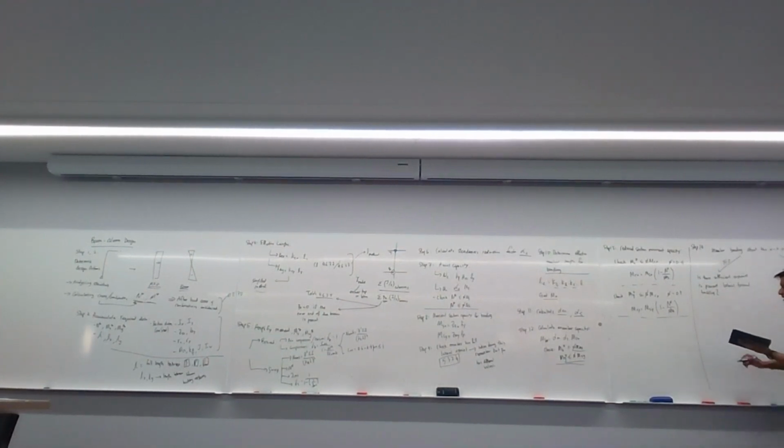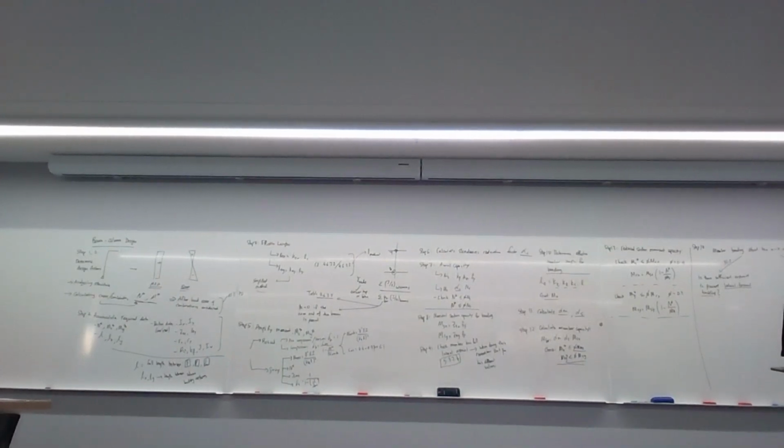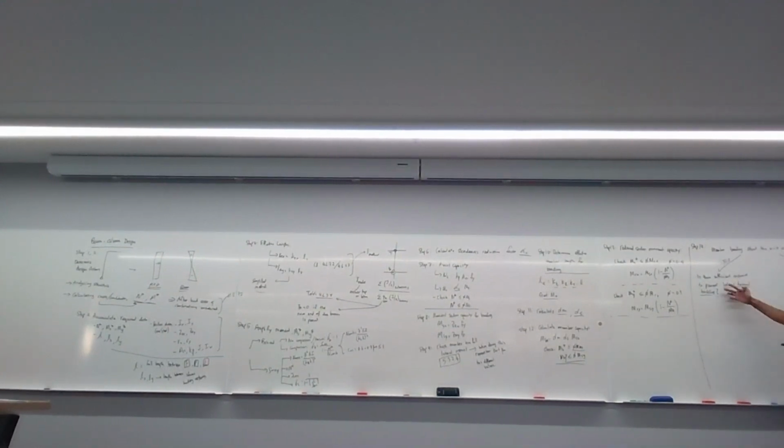Okay. Now, just note that lateral torsional buckling here is not the same as column buckling. Lateral torsional buckling is the type of buckling that's specifically for bending. It's flexural failure, flexural buckling. So you've got to ask yourself, is there sufficient restraint to prevent lateral torsional buckling?